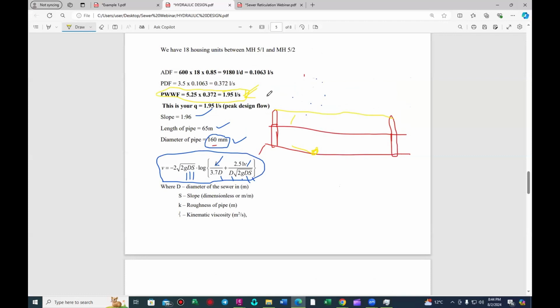Not everyone is going to take showers at the same time. Not everyone is going to do laundry at the same time. So this sewage is not all going to be produced at the same time. If I take a shower, probably I use 80 liters of water, and 85% of that water is going to be generated as sewage, flowing into my sewer line. But that does not necessarily mean it's going to reach cleansing velocity already. Please take note of that. It does not instantaneously reach cleansing velocity because it does not have sufficient flow to reach cleansing velocity in one go of its production.